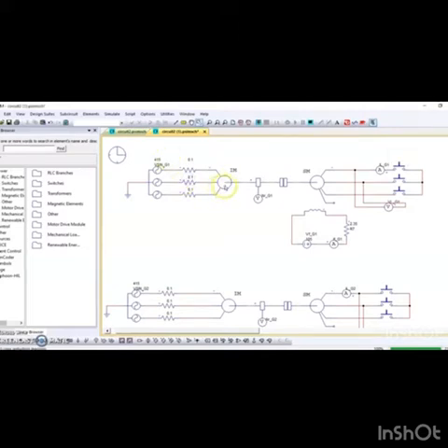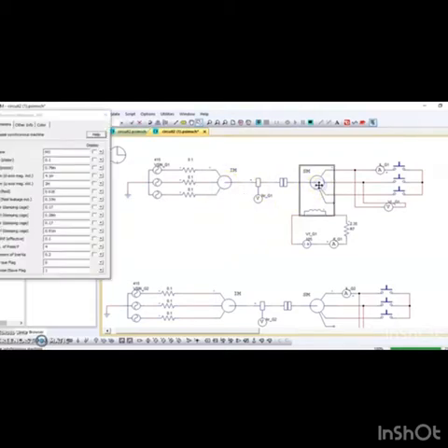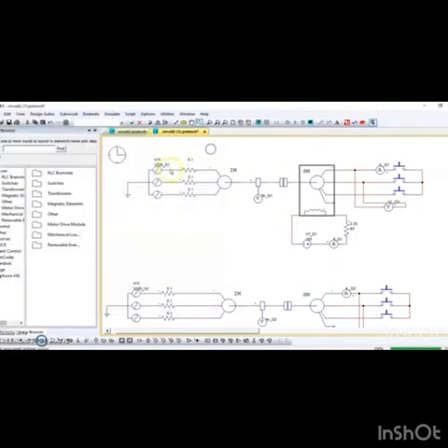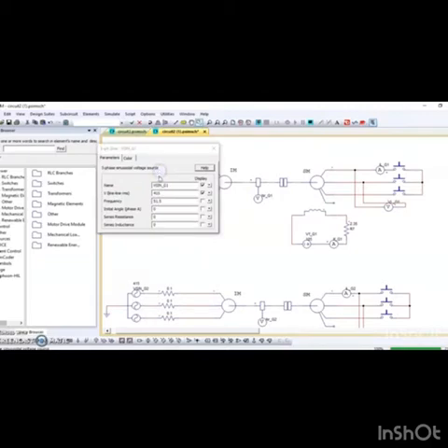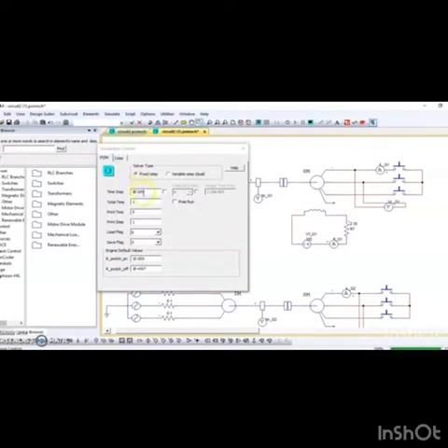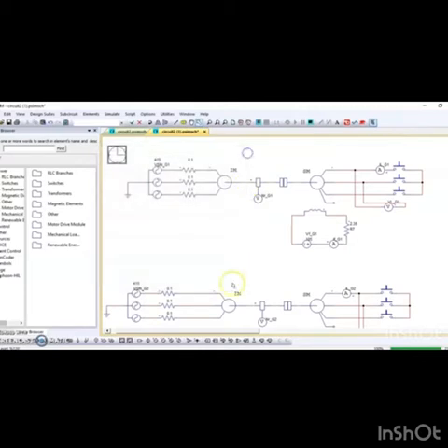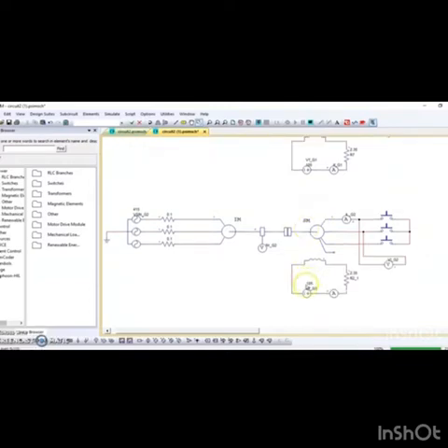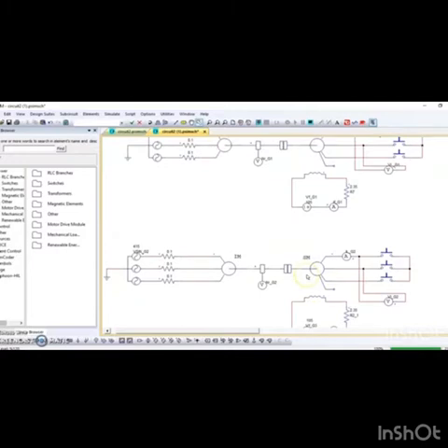and then we set the parameter of induction motor and synchronous motor. The frequency for generator 1 is 51.5 and generator 2 is 51. For simulation control, we set the total time to 3 and the VF for generator 1 is 105 and generator 2 is also set.